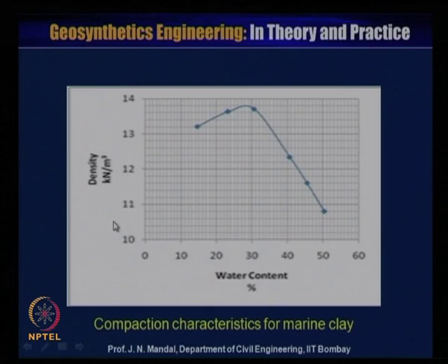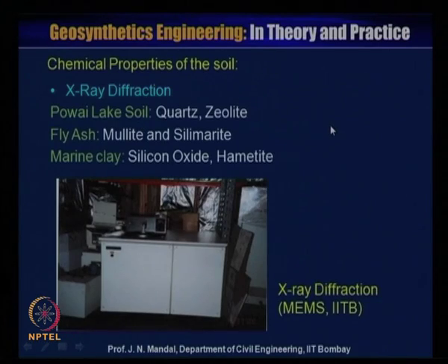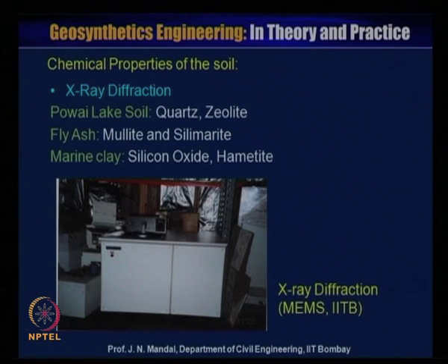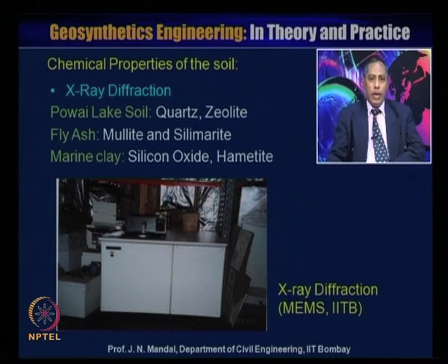And this is the compaction characteristics for marine clay. So, you can calculate the optimum water content and the corresponding dry density of marine clay. Now, we have also performed a chemical property test of the soil, that is X-ray diffraction. For Powai lake soil, that is quartz and zeolite, fly ash, mullite and sillimanite, and marine clay, silicon oxide and halite. This test has also been performed in MEMS, IIT Bombay. This is the X-ray diffraction equipment.